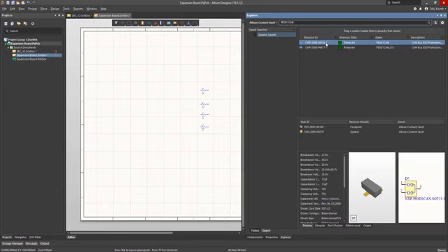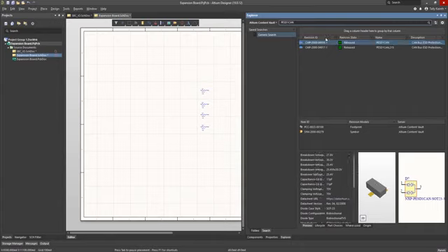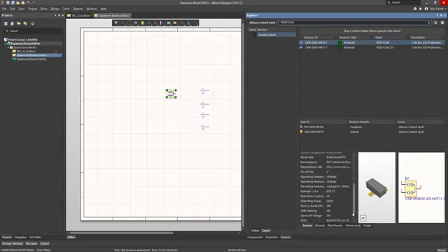In the Altium Content Vault, we can see a lot of detail for the components, including footprints and schematic symbols, as well as links to datasheets. Right mouse click on the part entry and select Place to add this part from the Altium Content Vault to the schematic. To further explore this panel, hit the F1 key for the online documentation. We will place the protection diode on the schematic and continue with the search for a few more parts.